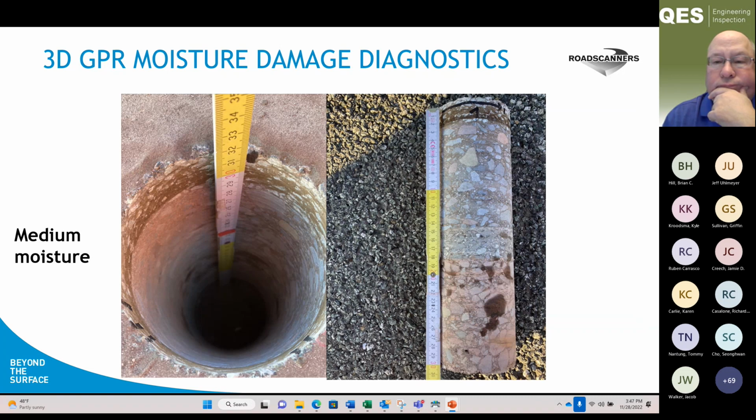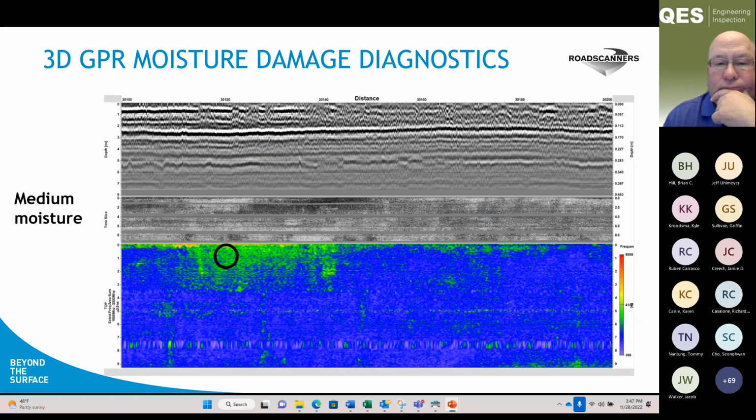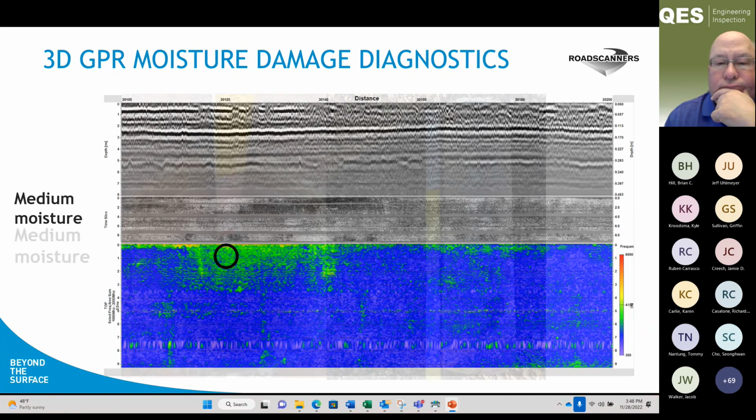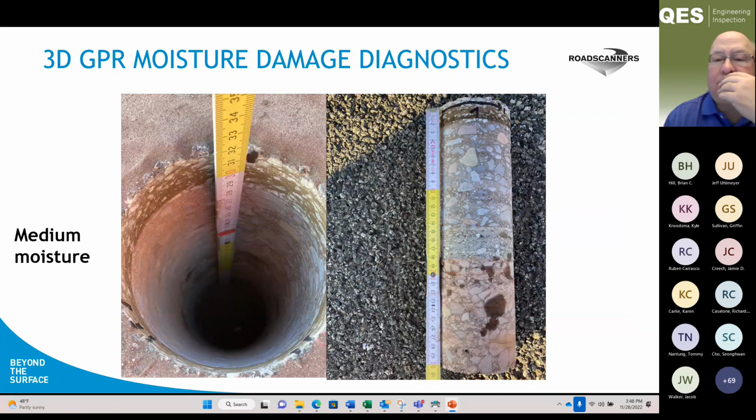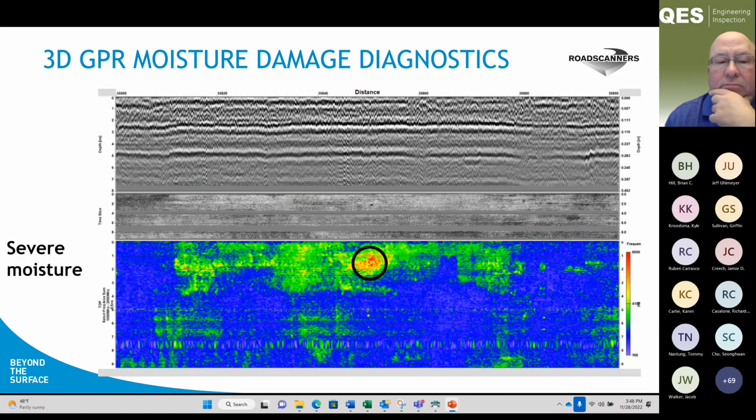This is again, if you show the previous slide again, you see that this is related to the road shoulders. So there's a verge. You should go and tell the maintenance crew to fix the verge. Don't allow the water going there. Fix the drainage, you save a lot of money.